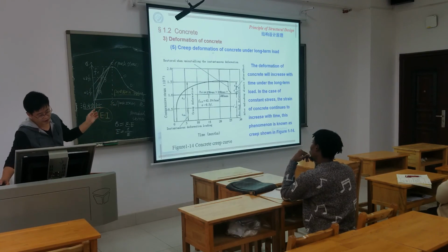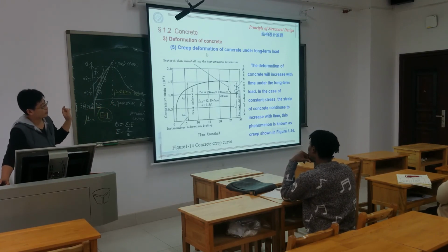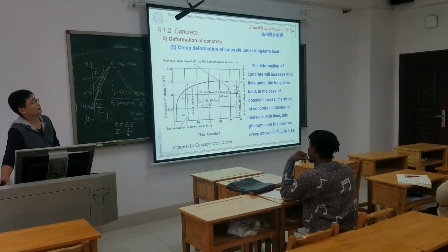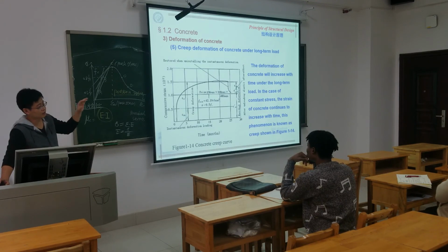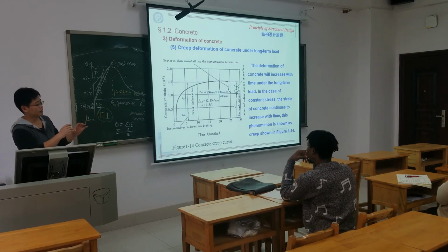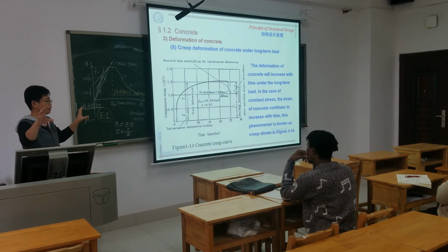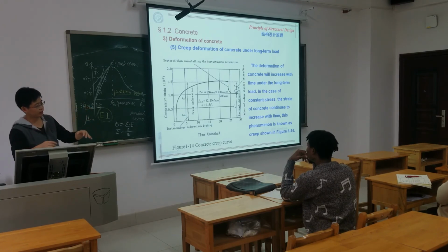The creep deformation is the situation where the load condition doesn't change, it keeps constant, but the deformation keeps developing. So the deformation increase is not induced by an increase of the load. The total load doesn't change, but the deformation gradually increases.